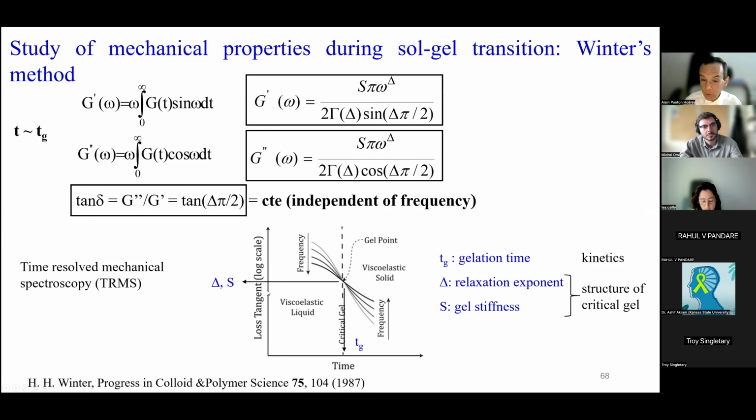And by plotting the ratio as a function of time for the different frequencies, you observe a crossover. From the crossover, you can deduce the gelation time, and from the projection on the ordinate axis, you can deduce the gel stiffness and the relaxation exponent.